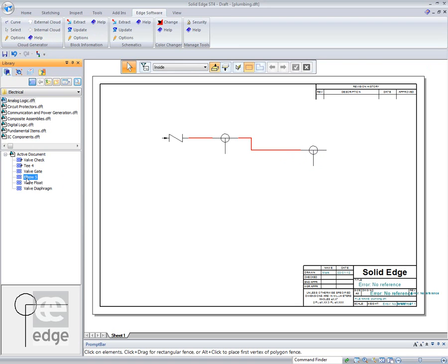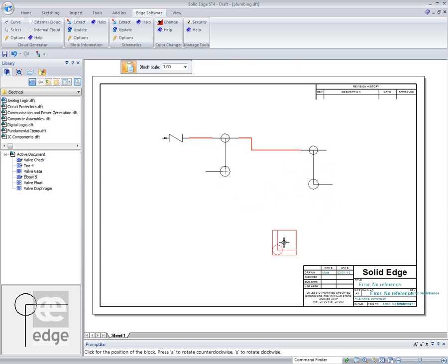I want to put an elbow in here, so place the elbow. Now I'm going to do a direct connect on this elbow. I want it that way. So it's like so, and put the other one round the other way. Oh, I could have done the S, couldn't I? Just think about it, put it there. And I might have then a valve, a gate valve associated with those.